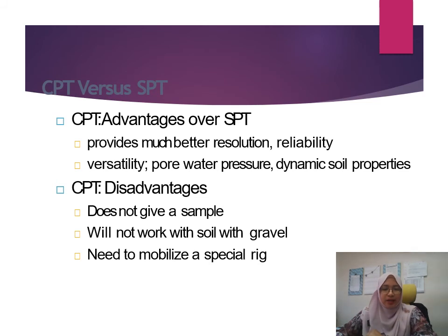The disadvantages of CPT: we cannot get a soil sample from CPT, it will not work with soil with gravel so it is not suitable for gravelly soil, and we need to mobilize a special rig to move the equipment.